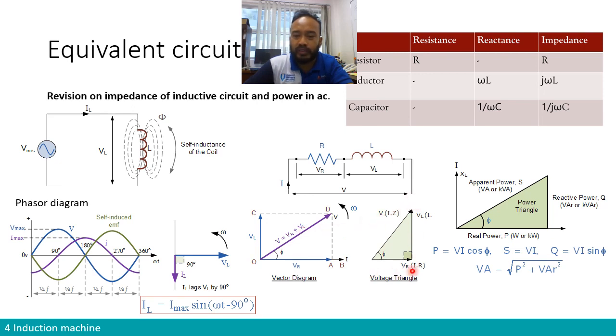This is what we call the voltage triangle. There is a component of voltage created due to the resistor, so it's a relationship between current and resistor. There is a component that's perpendicular to it due to the reactance. In this case, it's only an inductor. This is what we call the reactive part, and both of them create the total sum of those vectors. Basically, the real voltage.